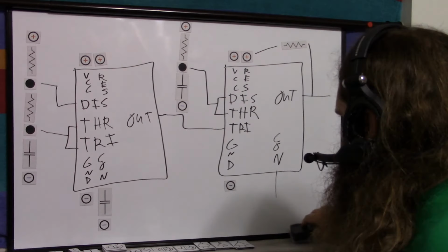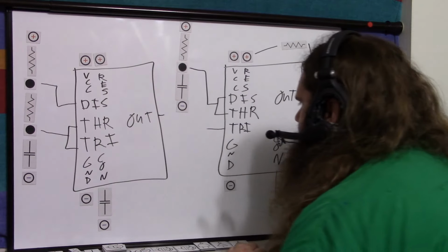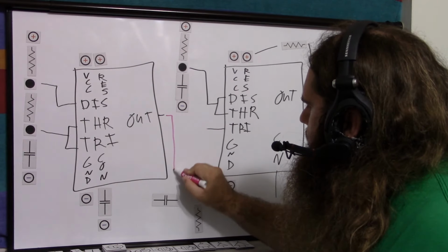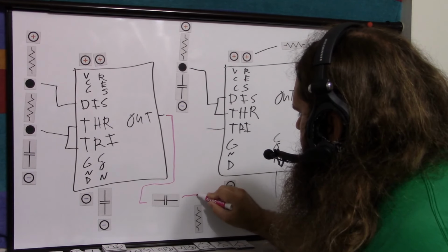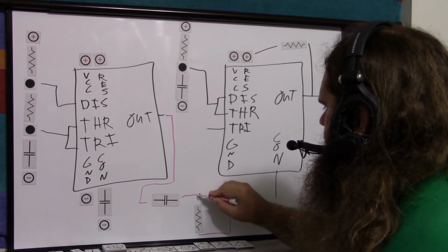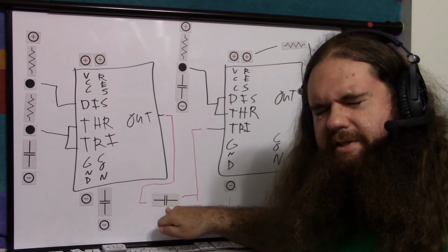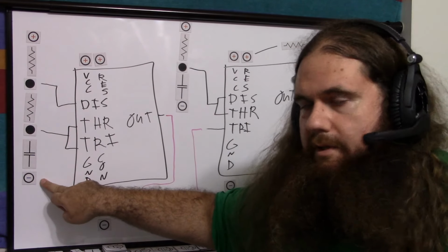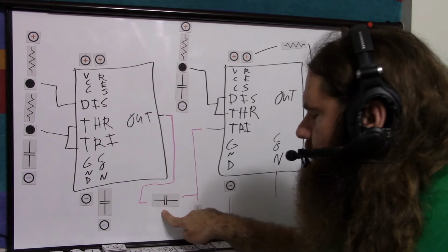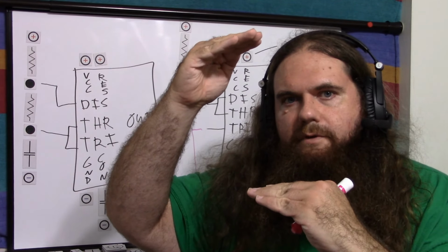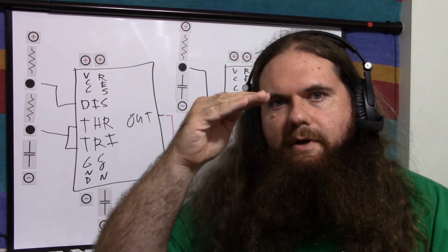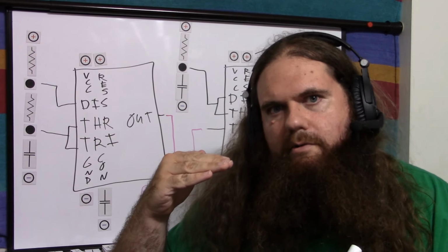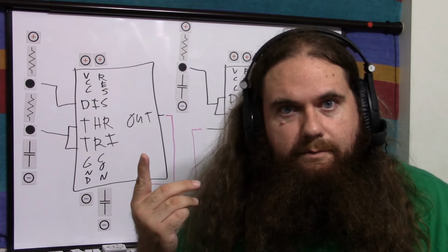The problem is, this is the way you hook it up. A high-pass filter is a series capacitor and a parallel resistor. So you take your output and you put it into the capacitor and you hook that across the resistor. Resistor goes to negative, resistor goes to trigger. This series capacitor removes the DC bias, right? So if you're using 0 volts low, 5 volts high, if you run it through a series capacitor, that 0 to 5 volt signal becomes a negative 2.5 to 2.5 volt signal. So almost all of the time, the signal is actually at 0. Almost all the time. Obviously, we've just failed.